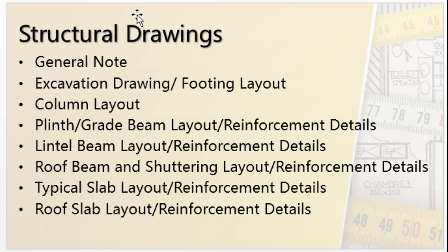There are structural drawings. Structural drawings will contain the general note giving some idea about the material properties which have been used in the design. The excavation drawing, footing layout, column layout, plinth or grid beam layout with reinforcement details will be given there, as well as beam and lintel layout with reinforcement details.